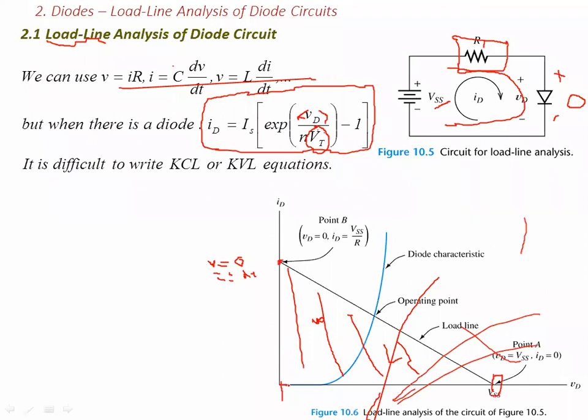Now, if you are given the diode characteristic curve, which we said has a value VD at which the current starts to increase, then you realize that where that curve meets the DC load line would be the operating point for that diode. If you get a diode curve of another diode which operates like this, then this will be its operating point.